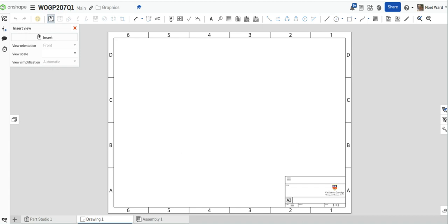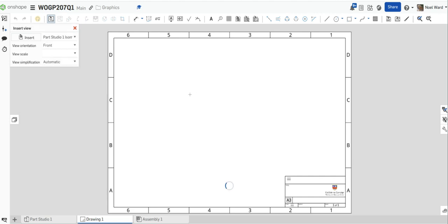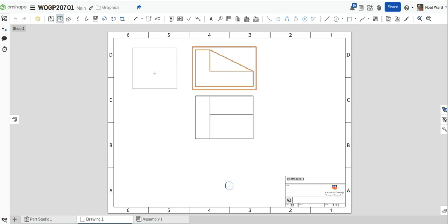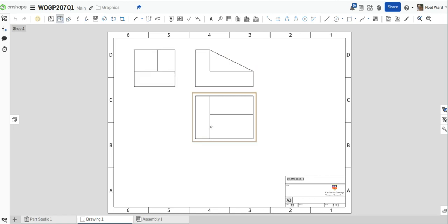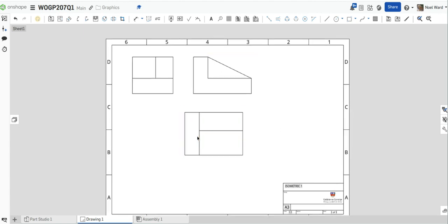Go to the drawing. I'm going to insert Isometric 1 now. I take that in, at scale 1:1, as you can see here. So I'm just going to draw. You can see from the book as well too that it was an elevation plan end view, and it was done in the format where obviously the plan's below no matter what. And then the end view was over here like that. And I'm going to escape that there now. And that's my elevation plan end view, which is grand.